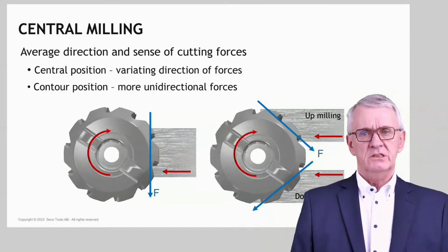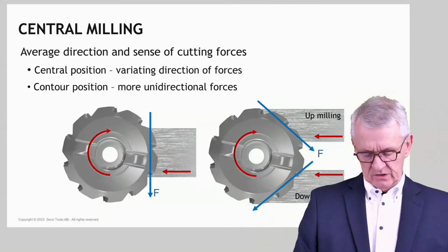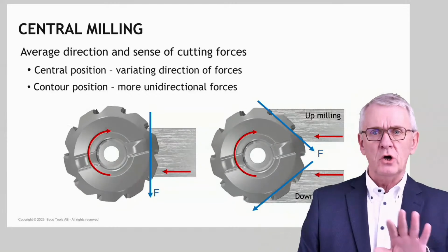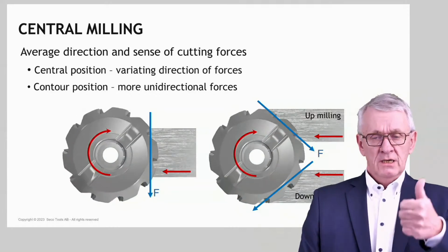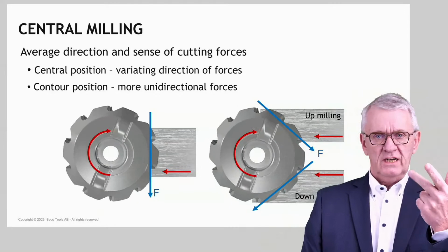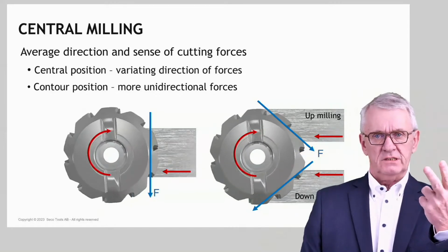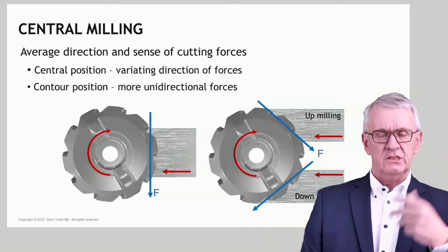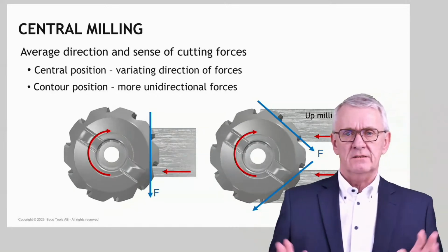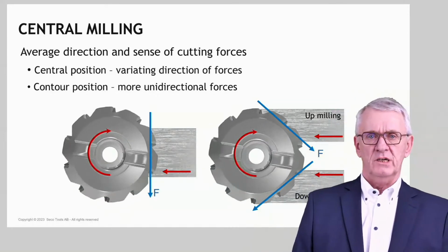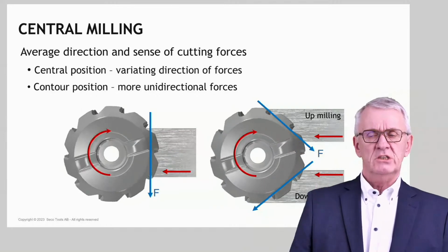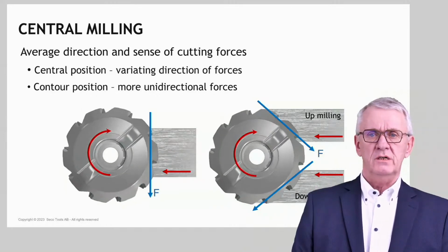We have already talked about micro vibrations in one of the previous sessions. Trust me, you don't want micro vibrations. Chipped cutting edges, short tool life, bad surface roughness, the risk that you enter a chatter situation: only negative things come from micro vibrations. So the situation to the left is to be avoided.